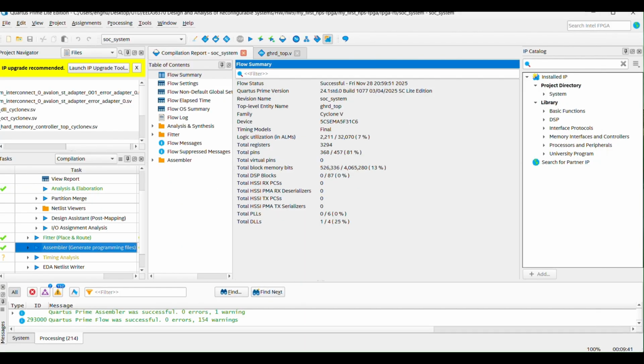But before downloading the SOF file to the FPGA fabric, we need to finish some steps on the C program compilation, because the VGA controller of the Cyclone of the Terasic board lives in the FPGA fabric, not on the HPS.